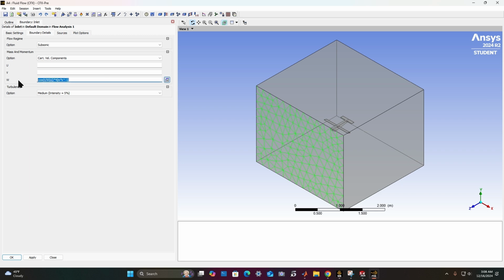And then we're going to copy this equation and put it in the v or y section and change it to negative sine so the flow comes down onto our plane. So I've edited the time to be t over 25 seconds just to make it run faster, and set the u velocity to 0.